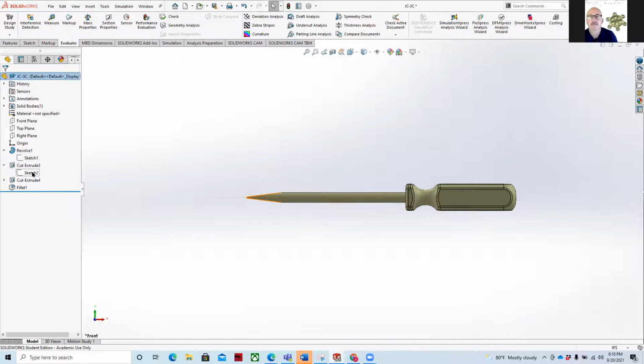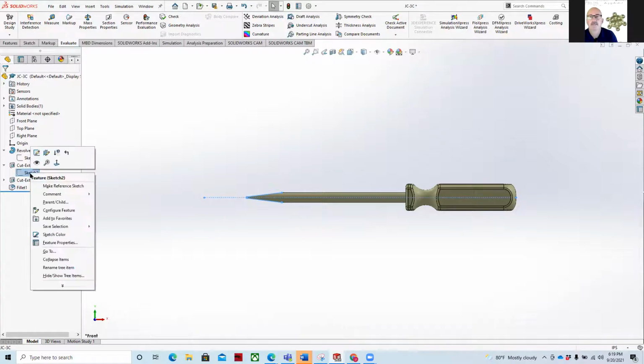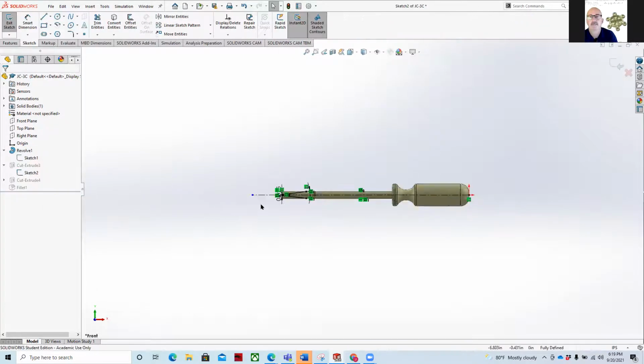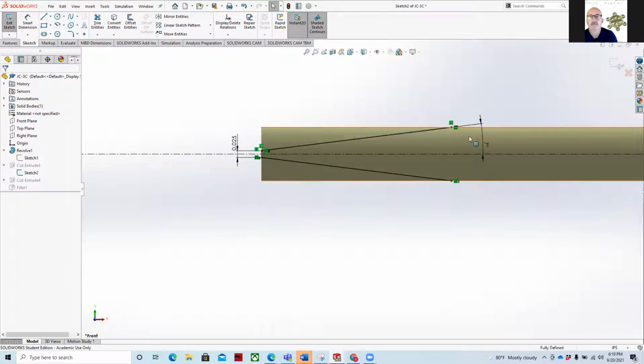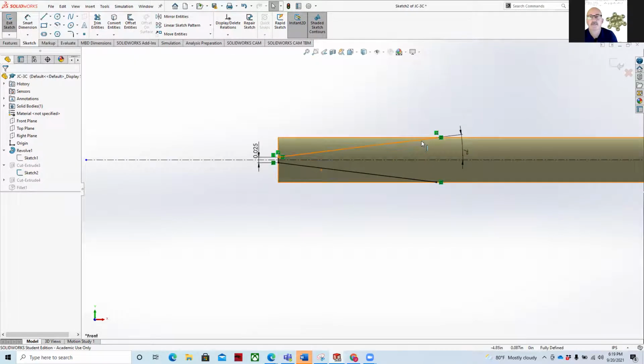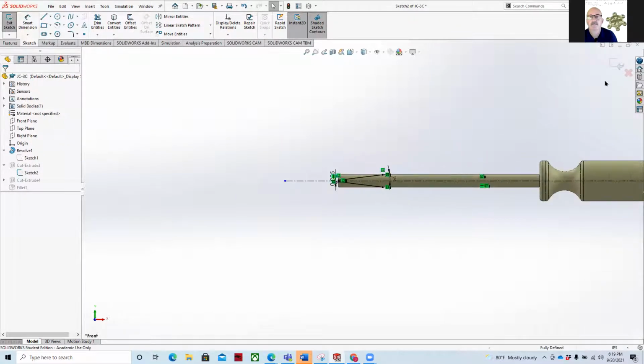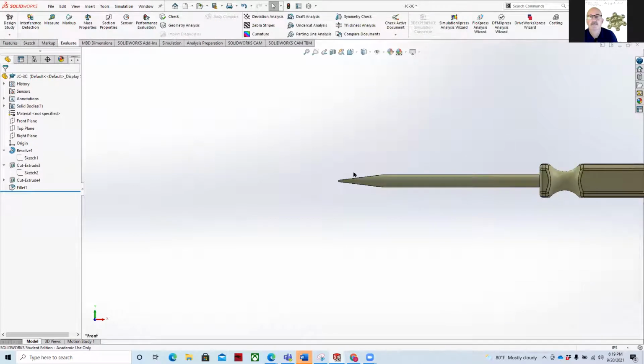And then we have these cut extrudes. And the cut extrudes, when you look at them on this edge, let's edit that. There's a couple of ways to do this. I had some trouble when I did this. And so what I actually did was create a triangle like this that would go about it, and then I would just extrude cut each edge. So if you do have any difficulty with that, you can also create the negative geometry to be removed. And so that's that component, not too difficult.